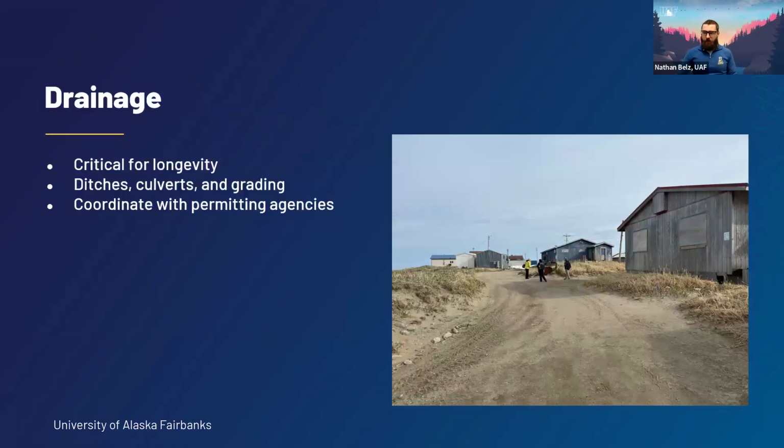Next slide. Drainage. I always tell students in my highway design classes that the three D's of good road design are drainage, drainage, and drainage. So proper drainage is critical and crucial for a number of things: maintaining safety, preventing erosion, and just prolonging the lifespan of the road in general. When I say drainage, I'm talking about structures like ditches, culverts, in some cases, storm sewers, bridges, things like that.